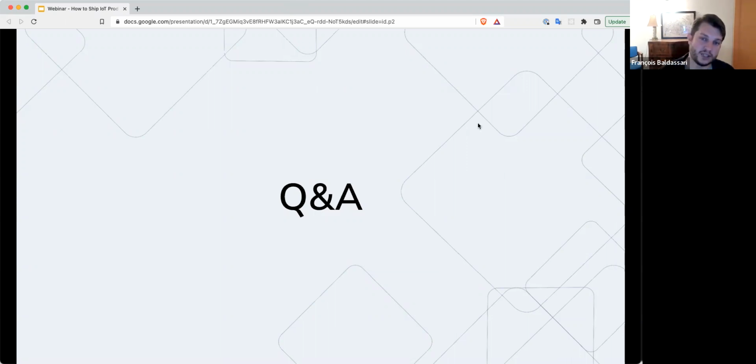Jeet asks, how do you deal with day 0 updates when not all devices will be connected? Great question, Jeet. I think there are really 2 ways to handle this. The first one, if your device is capable of connectivity, is to have a connectivity step required at unboxing. So you say, in your manual and your guide at unboxing, you have the customer connect over Bluetooth to a phone or something like that, using maybe a side channel that isn't how your device is typically operated, and guide them through an OTA flow by asking them to connect the device somehow.